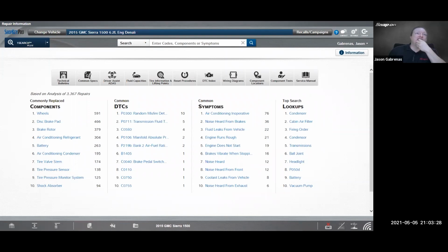Could a shorted bus cause damage to a scan tool or a scan module? It depends. I'm going to go with it depends. Because I think we've probably all heard the stories before. The Volkswagen, you put an aftermarket radio in. These are older Volkswagens, not newer ones. If you put a radio in the wrong Volkswagen, it would send 12 volts down a line. It's supposed to not see 12 volts. And yeah, you could fry a scan tool that way. I think by now, at least our scan tools have protection in there where it wouldn't happen. But you never know, right?